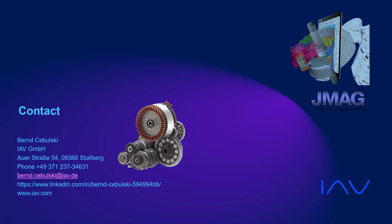Tianjie Zhou from University of Nottingham. Basically, during the development of PMSM, we have realized that the most significant challenge in reducing the permanent magnet usage is not in achieving its peak performance, but in the design task of reducing the demagnetization issue. In most cases, we have been asked by our research partners to cover the situation where an active short circuit happens with a very high peak current transient. And at this kind of challenging operation point, we need to limit the demagnetization ratio to be below, for example,